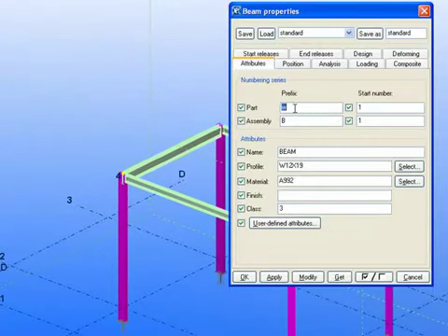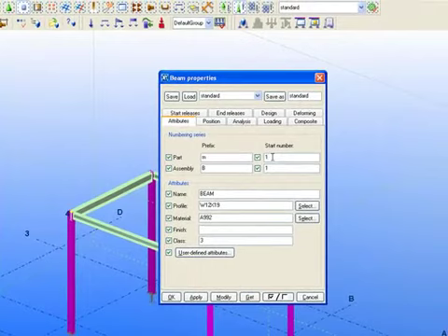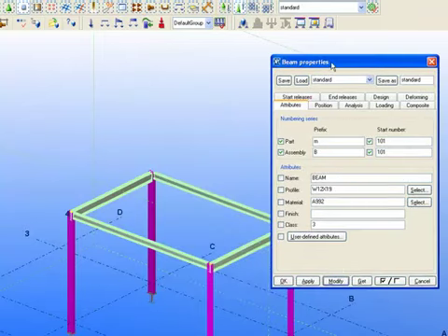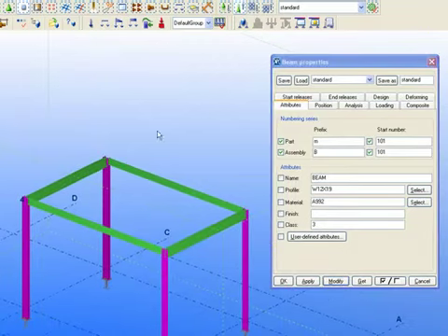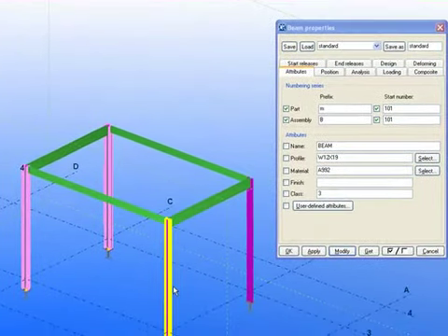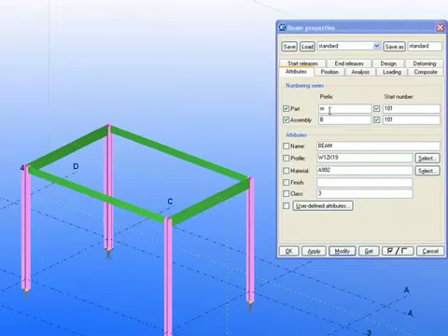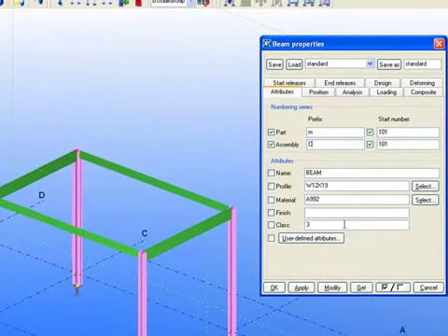Let's make our beam small m. Let's begin with 101. Beam is B. Start number 101. Make sure you uncheck everything and only check the member or the part that you want to change. Okay, that's the number one rule there. Uncheck everything and only check the member you want to change. Apply. Now let's select the column. Let's change that to still small m, and the assembly prefix is capital C, 101.